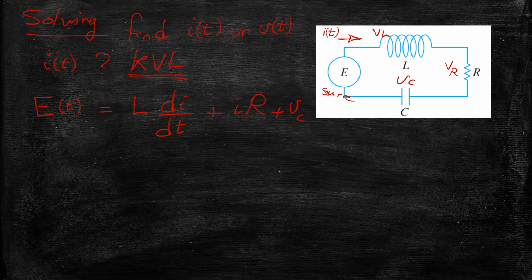So we have the direct relation: if we have a capacitor, the current itself is C dV by dt, in the time domain. If we need to get this voltage as a function of the current, V will be equal to 1 over C, the capacitance of this capacitor, and then instead of this derivative, we will take the integration of I dt. This will be from 0 to any time t in general.